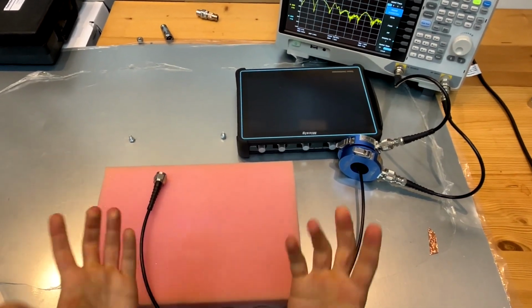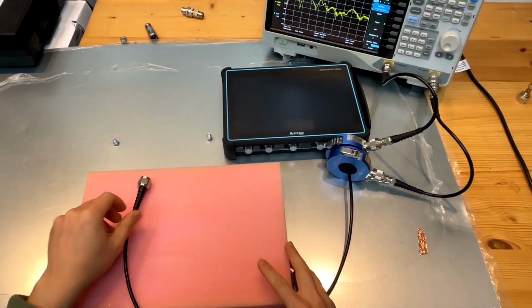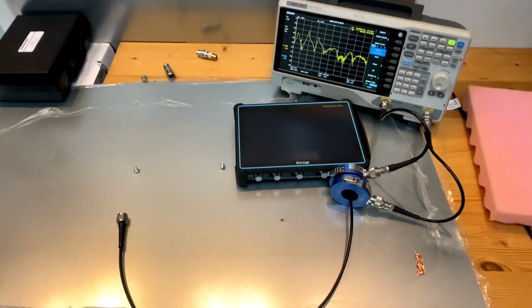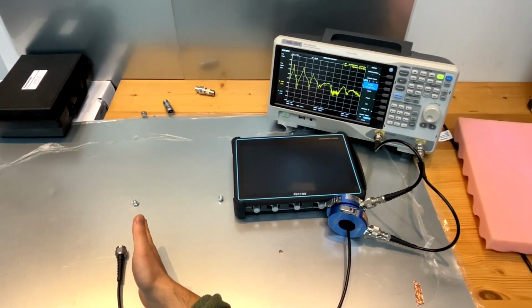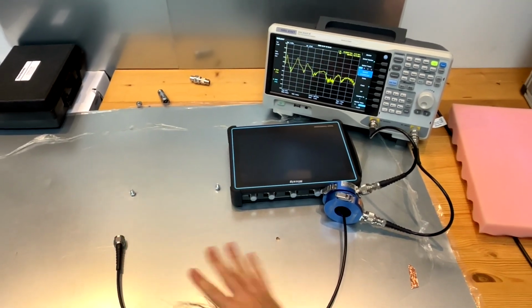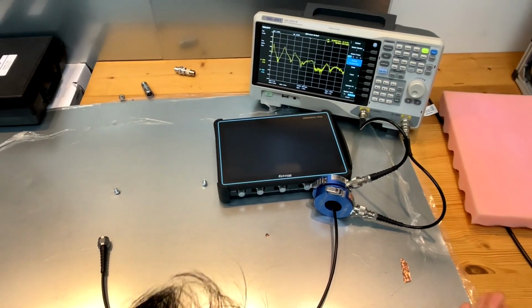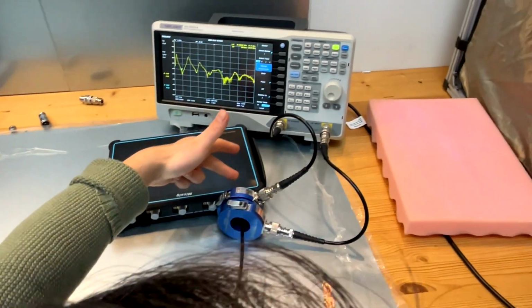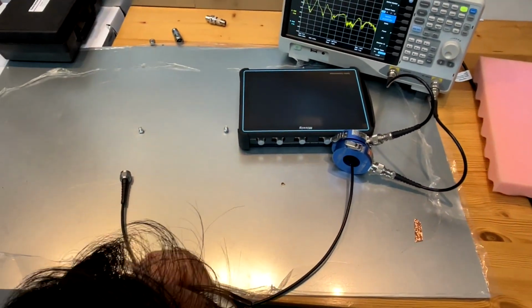What if we also provide a low impedance common ground to this end? Let's have a look. See that changing again. I'm just putting this on the common ground, so it's not a really good connection, but you can already see we shift the resonance frequency again, because now this end has a lower impedance and this end also has a lower impedance to this common reference.